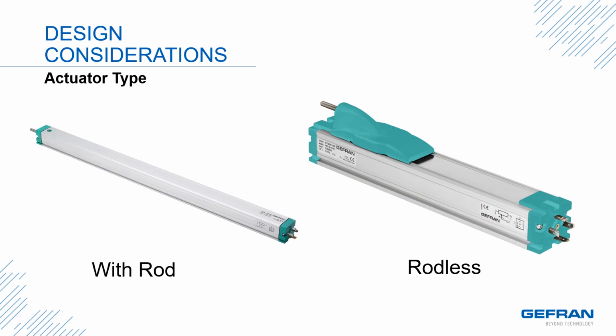The next design consideration is actuator type. Potentiometric linear transducers are typically available in one of two actuator types, with rod and rodless. If a transducer is selected with rod, the application must be able to accommodate the full length of the sensor body plus the full extension length of the rod. In rodless designs, the mechanical travel is within the length of the sensor body, so it is more compact.